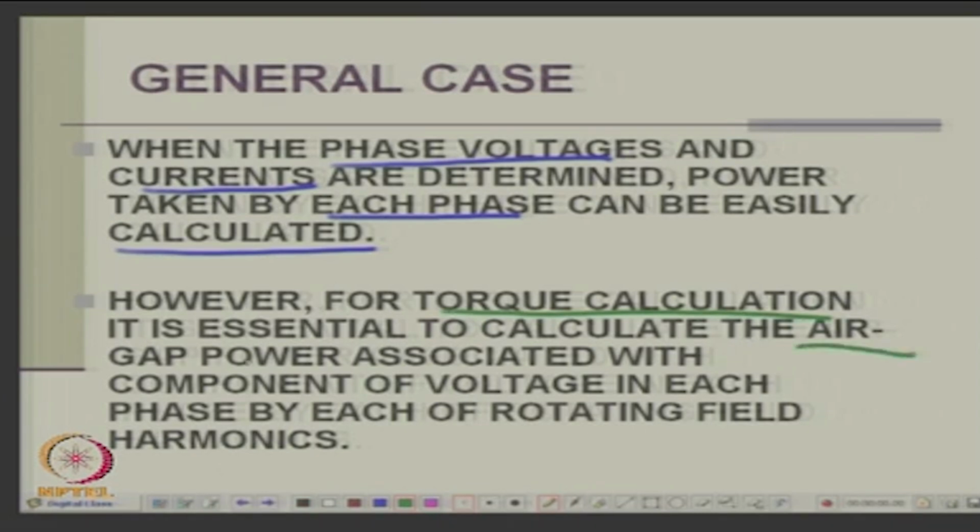then you calculate the air gap power. Air gap power is that minus the stator power, air gap power for each of the fields, and then component voltage, and then you calculate the power into the forward field, all the 3 phases for each of these. Okay.